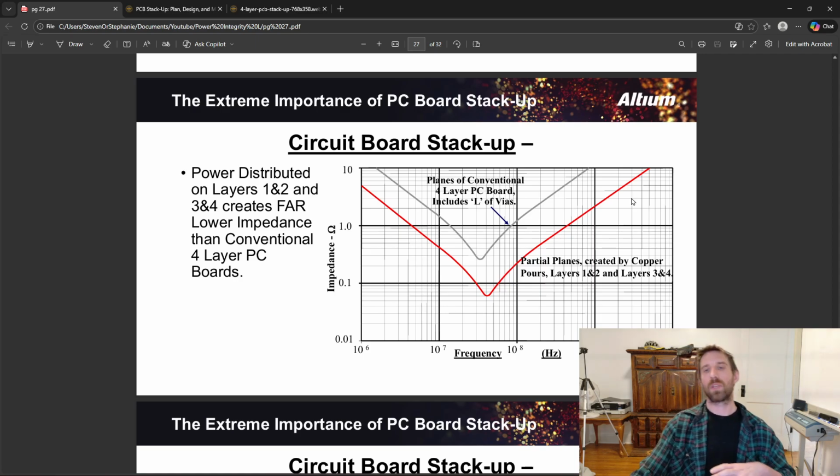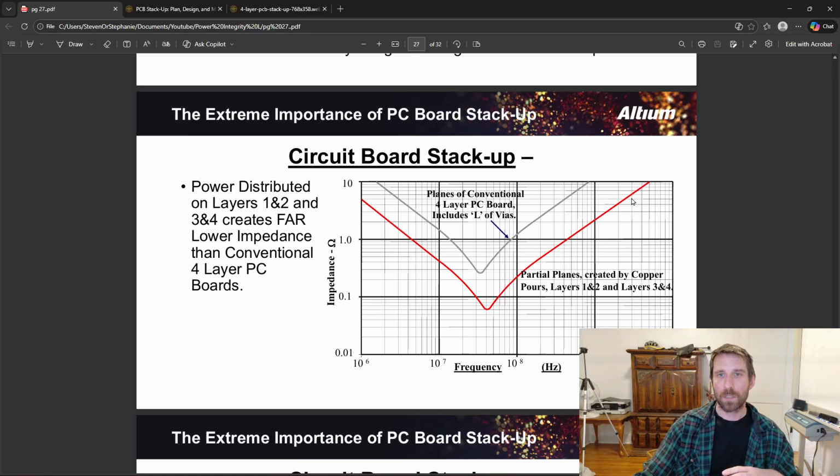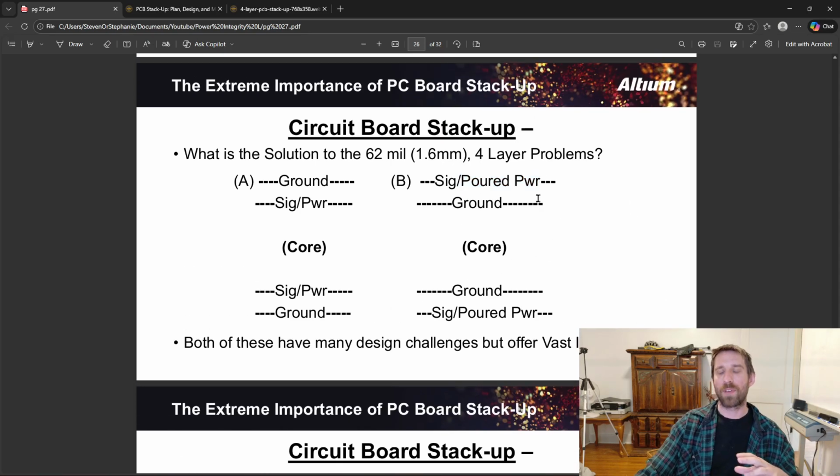So not only that, what your board manufacturers are going to want is a balanced board. So your inner layers, whether it's power or signal, that part is balanced because it's just a big piece of copper at the end of the day. But with your outer layers, your signal layers, that can be a lot different.